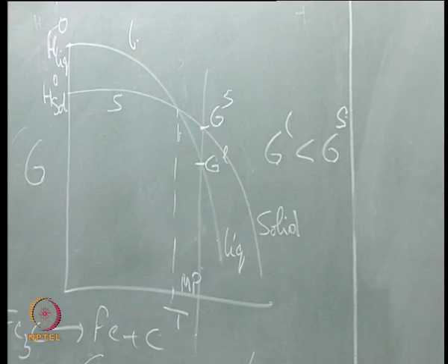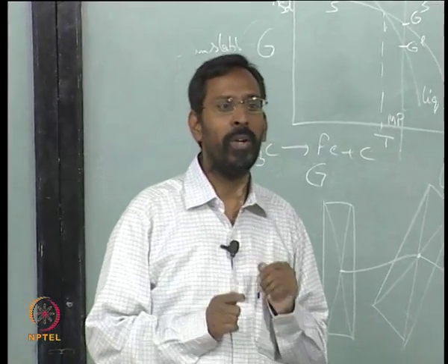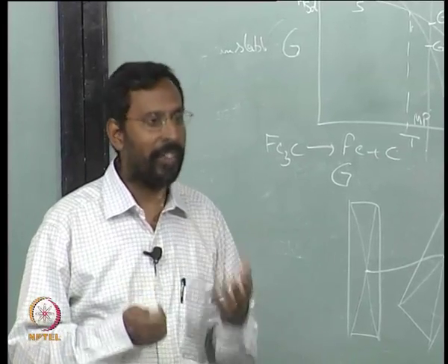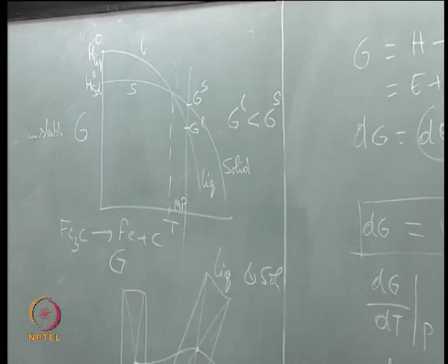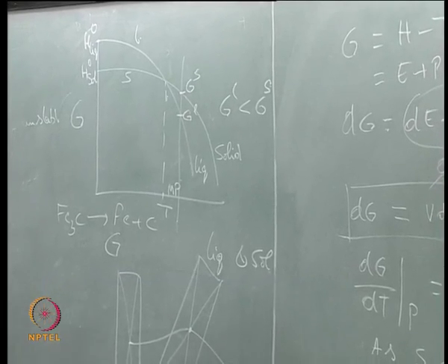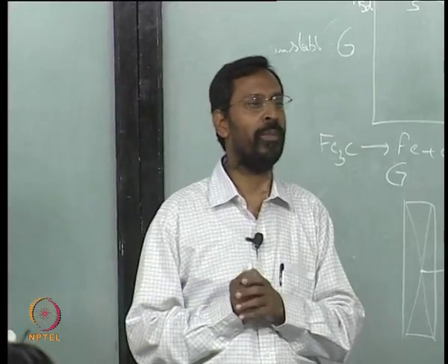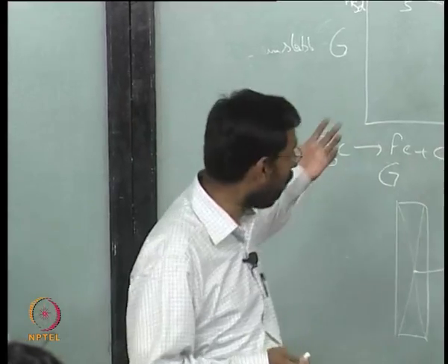It is possible that the solid can still remain as a solid, which we call a metastable solid, if the conditions are not ripe enough for the solid to become a liquid. In the case of solid to liquid this does not usually happen, because the solid to liquid transformation is much faster than the liquid to solid transformation. You see the reverse happening more easily.